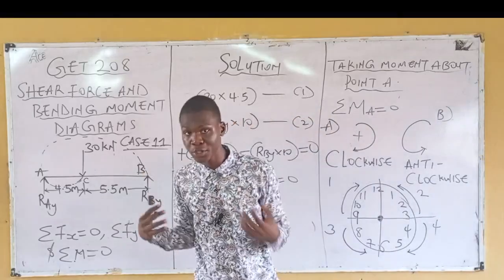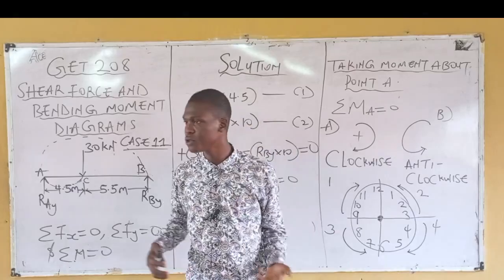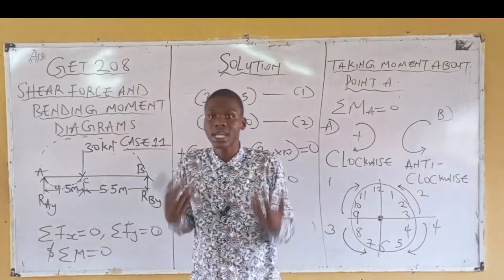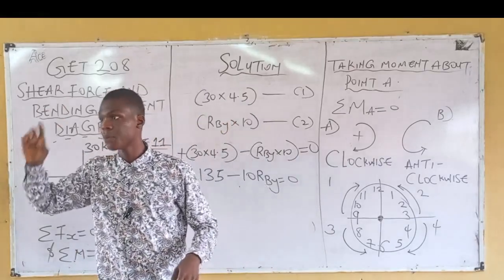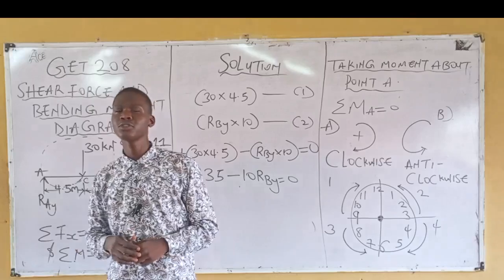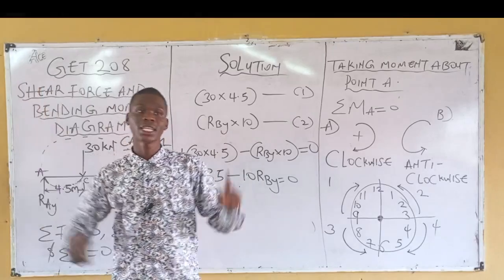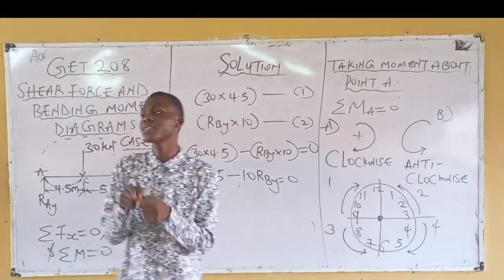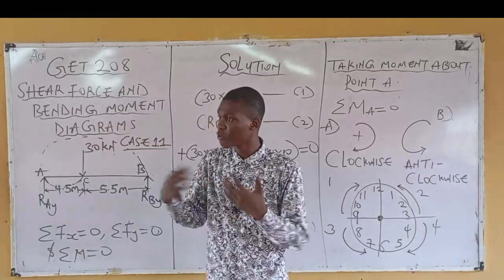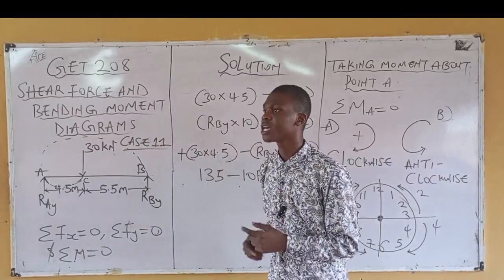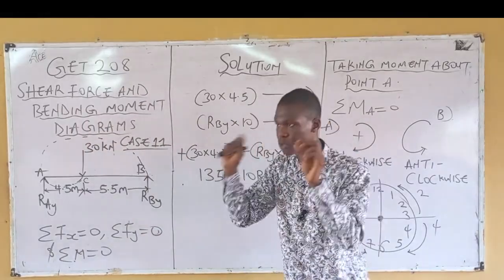When you did Kirchhoff's law, we said that from positive to negative, you have it as positive, meaning voltage gain. Negative to positive, you have it as minus, meaning voltage drop. In my video, if you check the comment section, they are saying that when they check other videos or search online, they are told the reverse. Both of us are still correct, because as long as we stay consistent with our sign convention, the end product will still be the same.